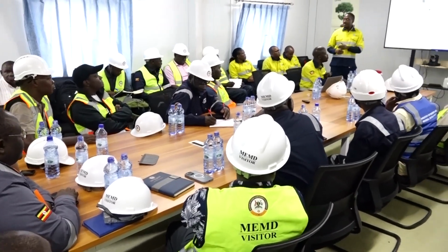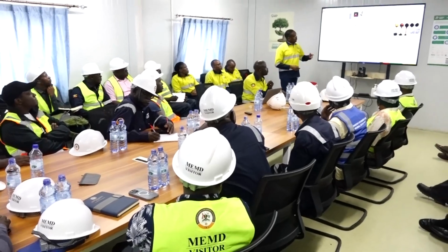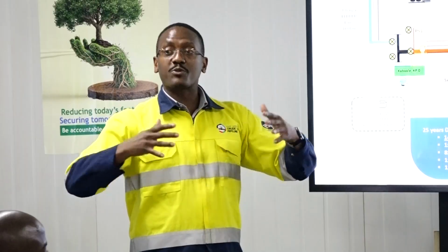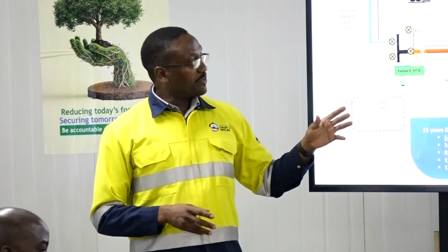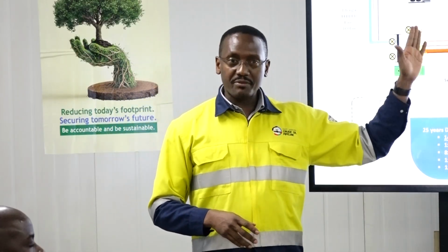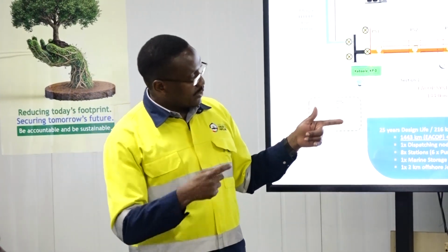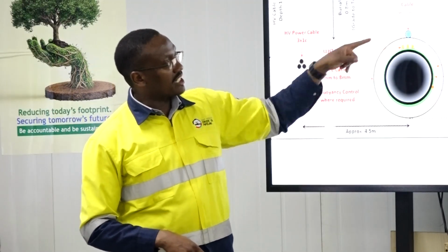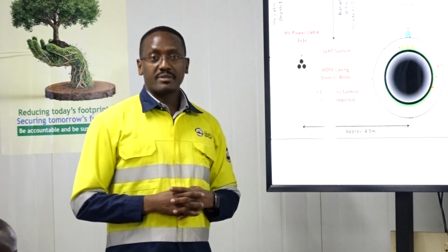For environmental issues, because the oil is waxy, it does not flow. The moment it comes out, from 50 degrees to 27, it will not flow for a long time. But these pumps are powerful. If you're pushing 230,000 barrels per day, you should be able to stop, close the main block valves and control immediately. Along that, we will see on the next slide, we also have a fiber optic cable that has been laid with the pipe.